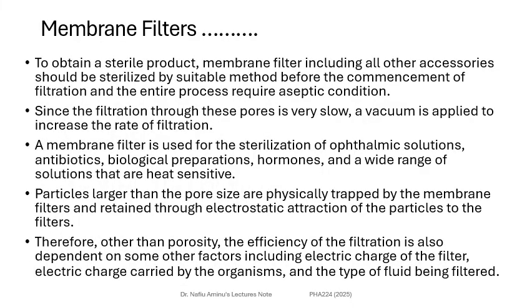To obtain sterile products, membrane filters, including all other accessories, shall be sterilized by a suitable method before the commencement of filtration, and the entire process requires aseptic condition. So these are physical substances, like the membrane filter I've shown before, which I will show in the next slide. Those components had to be in sterile form before the commencement of the procedure. Because if they are contaminated, they have some form of bacteria, those contaminating agents can end up in the solution we are trying to treat.